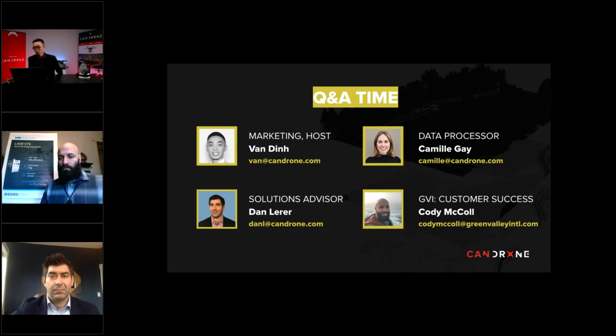So Jared asked, can you speak briefly on the coordinate system LiDAR is captured in, and whether LiDAR360 can get it in local coordinates? Yeah, so if you have a GVI system like the LiDAR V70, when you're in LiDAR reference, the base coordinate system that it's using is WGS84 and ellipsoidal heights. So that's the root origin from it. And then in LiDAR reference or in LiDAR360, there are options to reproject that data into a different datum or projection.